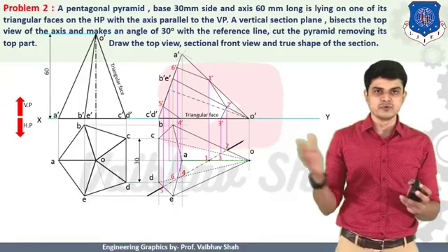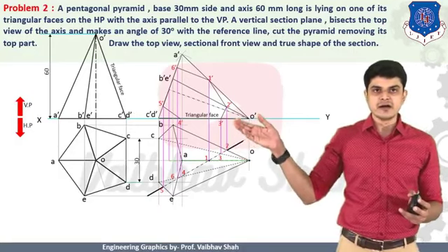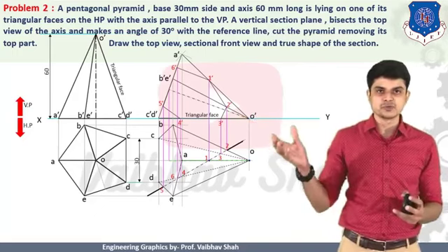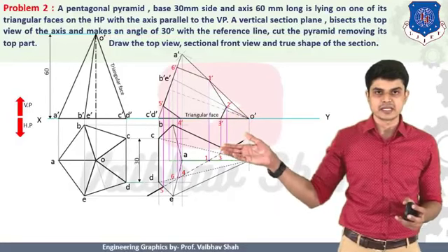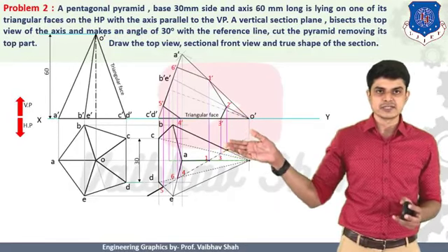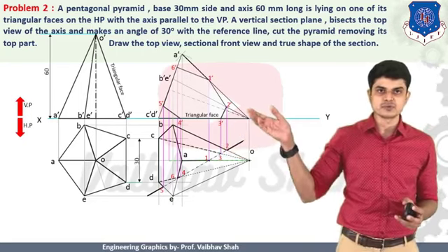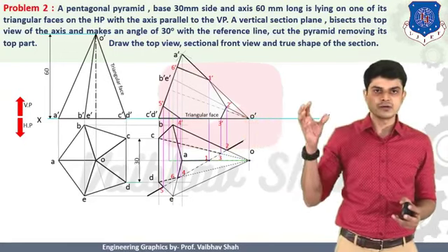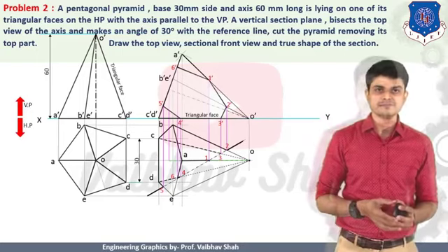After having the final, we should make the object on the left hand side of this cutting plane darker. And we should make the object after this cutting plane. So this is the remaining object with us after the cutting plane. So we should make that object darker, and we should show the hatching lines in the section like this. Let us make these hatching lines in the section. We should make this object darker on the left hand side of the cutting plane like this. Let us make this section darker. So it is showing that we are remaining with this object after cutting the object, and we should show this object by a darker line. This is nothing but how you should draw your object. So the lighter portion is showing that we have just removed that portion. We are left with the portion which is shown by the dark line. It is very much easy.